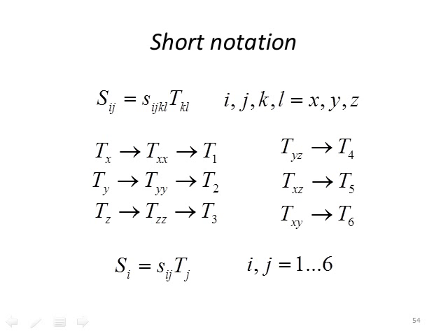And then we have to make a short notation to try to simplify these things. And this is basically, you can go through this on your own. It's very straightforward. Because the tensor had xx, yy, zz, then we make these terms consist of just x, y, and z. And then yz, xz, xy, these cross terms are given t4, t5, and t6 to simplify our notation. And then we get a new strain-stress relationship.